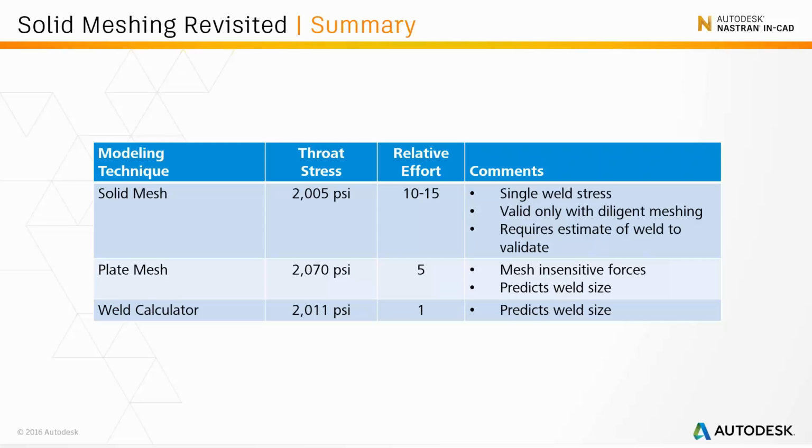And as we've tried to highlight, using the plate mesh is a great compromise for instances where the geometry and loading is too complicated for the weld calculator, and it gives comparable results but with much less effort and assumptions than using the solid mesh.